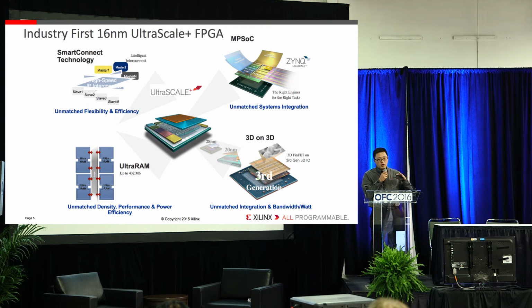Just take the case of the biggest device you will get from Xilinx in 20. You will get 60 25G IOs and 60 10G IOs. In 16 nanometer, you actually get 120 25G IOs. And those IOs are essentially sitting on a 3D stackable die.